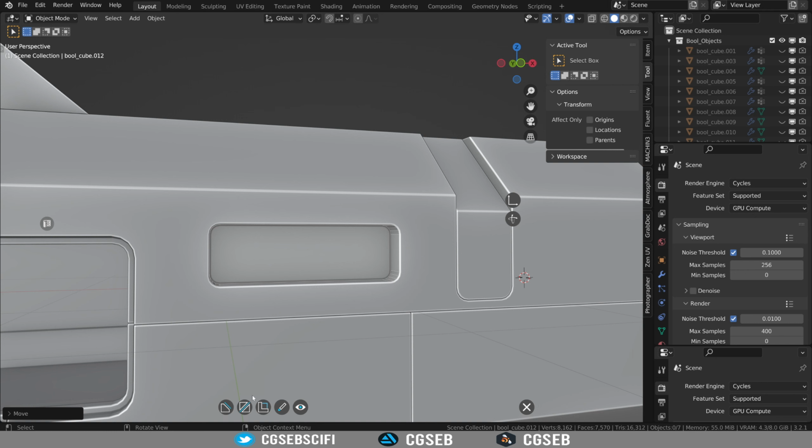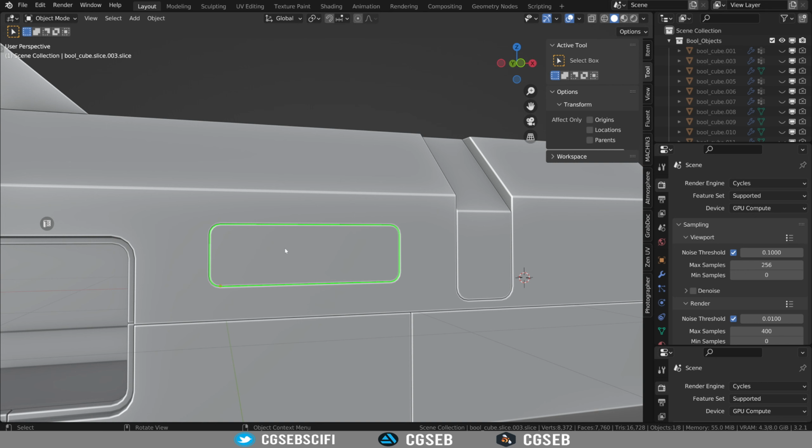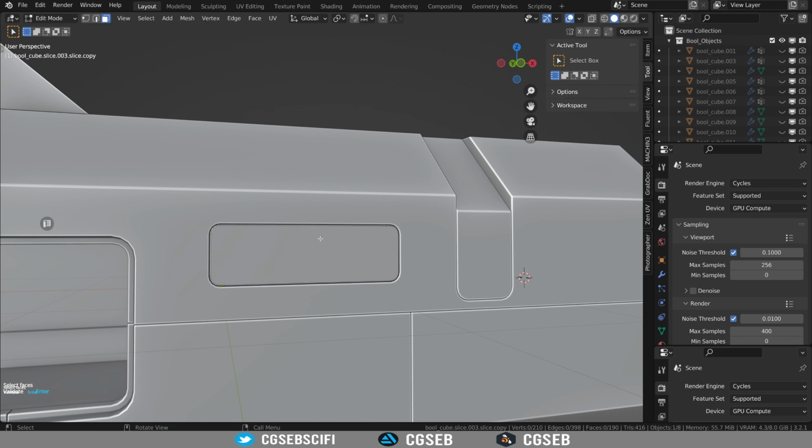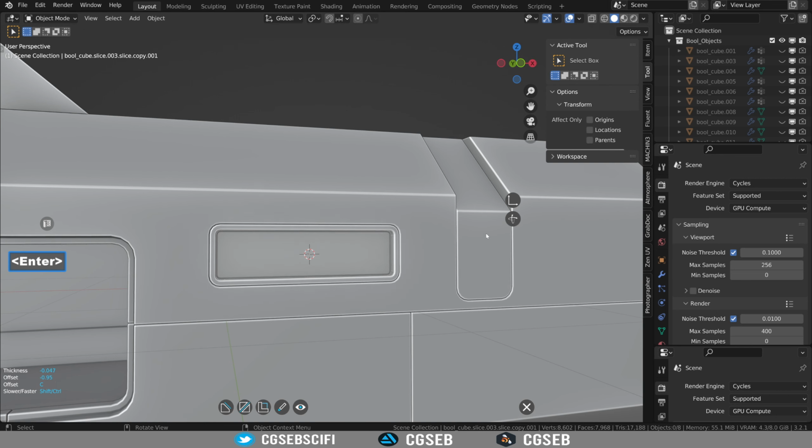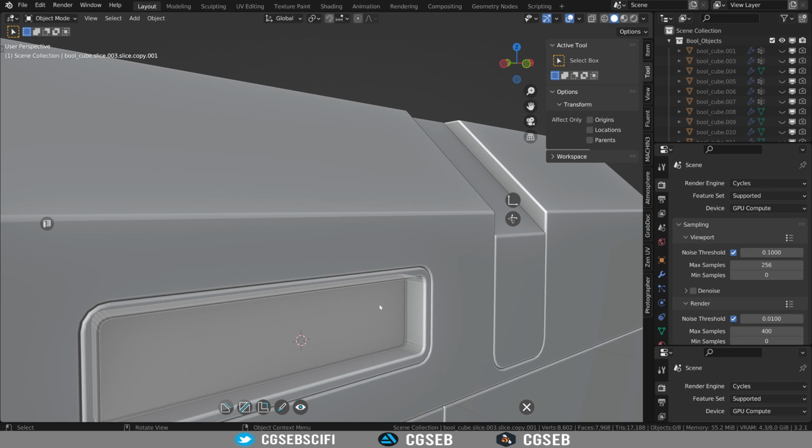and actually we're going to change it and move it to a slice. And now if you go to the slice, press F, cut, inset face inset, then you press I, you inset it, probably something like that. Press enter, go inside a bit. Good.